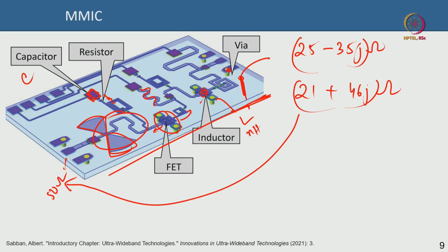Then it's basically matched. That matching has to be done through impedance matching networks, and radial stubs; these are called radial stubs, for instance, or maybe these are something else. There could be filters also, by the way. They have different kinds of components on an MMIC, so that the entire thing is an independent circuit on its own. Okay, this is just a schematic to show how an MMIC looks.